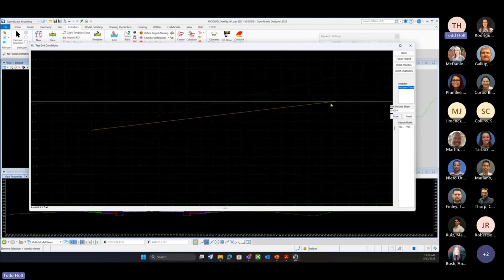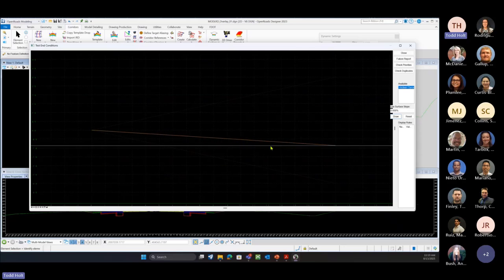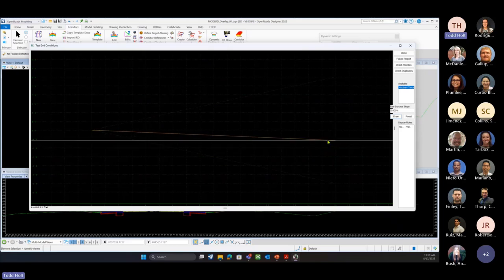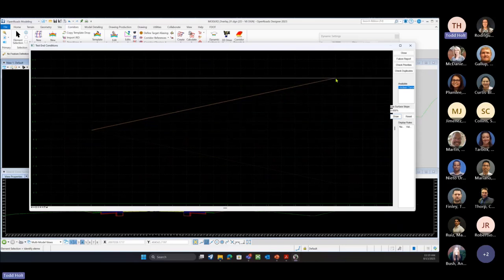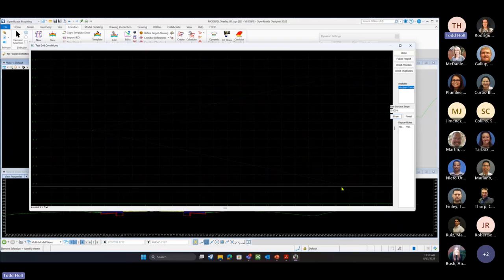So that's basically what we're going to draw in: we have a restriction or a clear zone for grading a right-of-way where a horizontal position of our tie-in is known, so 18 feet, but we want to have it develop a variable slope, either 3 feet above or 3 feet below that.